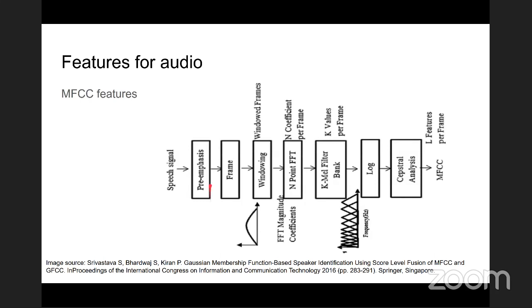The way it is used is, let's say you take the speech signal and you take its different frames. So that means you take, let's say, only 100 milliseconds at a time or 1 second at a time, and you will analyze that. So that's a frame, the window that you will analyze. And you will do some pre-emphasis, meaning you will suppress the high frequency and low frequency, because you don't think that contains your speech signal. And then you will compute the Fourier transform, and then you will basically summarize the Fourier transform in different frequency bands, which are arranged in a log scale.